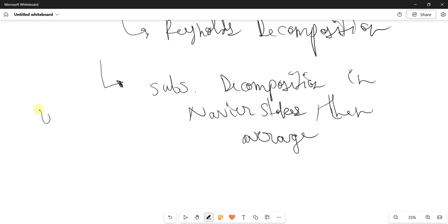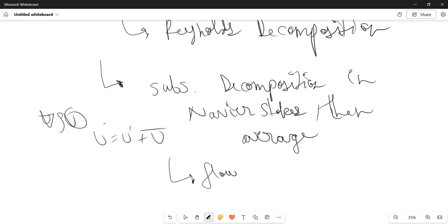So you have, if I'm not wrong, the del rho v. This v term you have to replace with u is equal to u mean plus u dash, right? When you do this, you get an equation, and then you average out the equations. Why do we need to average it out? This makes the flow equations easy to solve. So flow equations are now easier to solve, okay?